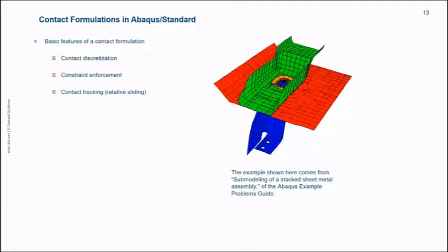And it was quite a challenge to account for the shell thickness and the stacked sheet metal. And of course, all of these problems have gone away more or less with today's algorithms, say in the general contact definitions that you can put into Abaqus Standard. You don't have to worry about enforcing the thickness of the shells and things like that. It just is a straightforward definition.